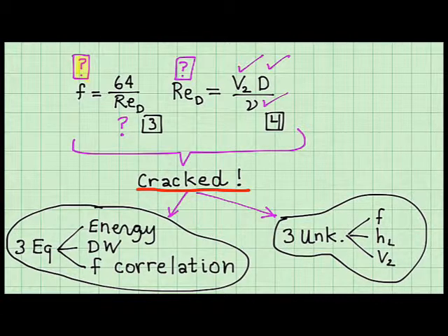I have 3 equations: the energy equation from 1 to 2, the Darcy-Weisbach equation for the head loss, and a correlation for f, which is the friction factor.